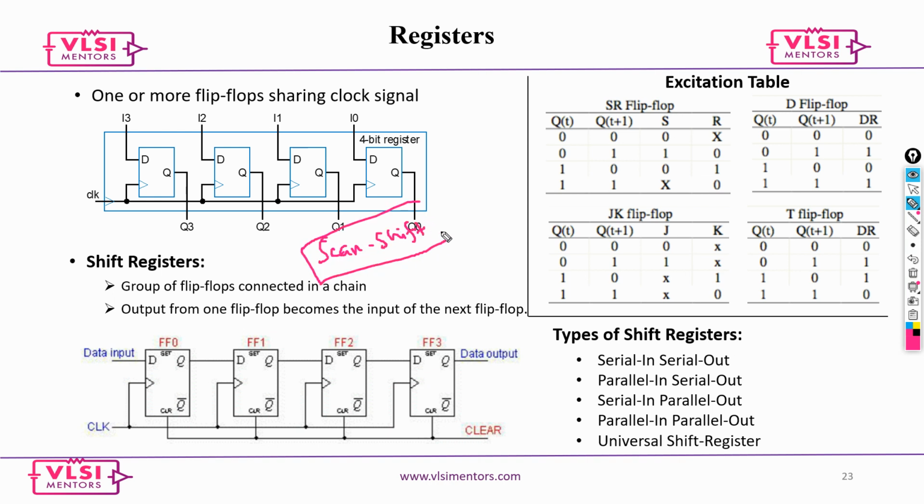This is something you will get to know when we talk about different modes of operation. There is a func mode, and then there is a test mode. The moment you go for manufacturing, your DFT part comes into the picture, right? So what is the guarantee that your Q is not tied to logic 1, or tied to logic 0?